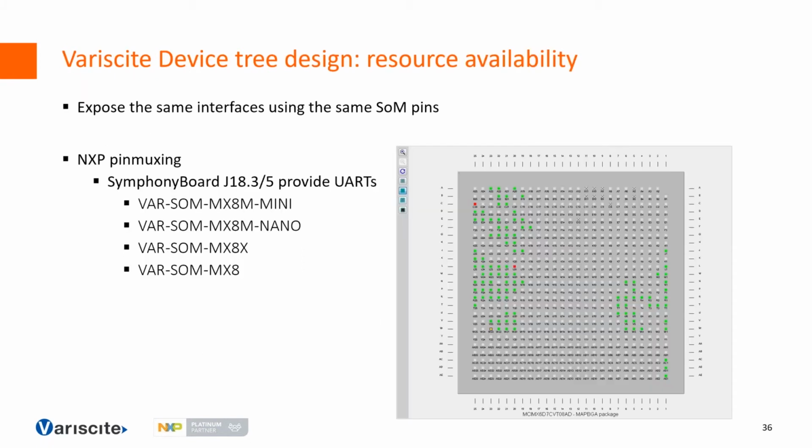So why is this possible? Because on several SOMs, we exposed on the same pins the same functionalities. Just for example, this is possible because of the NXP pin muxing capability. So each pin can expose a different function. Each pad can provide a different function. And for example, if you have a look at our Symphony board, the connector J18 at pins 3 and 5 always exposes a UART for all of the SOMs that you can connect.